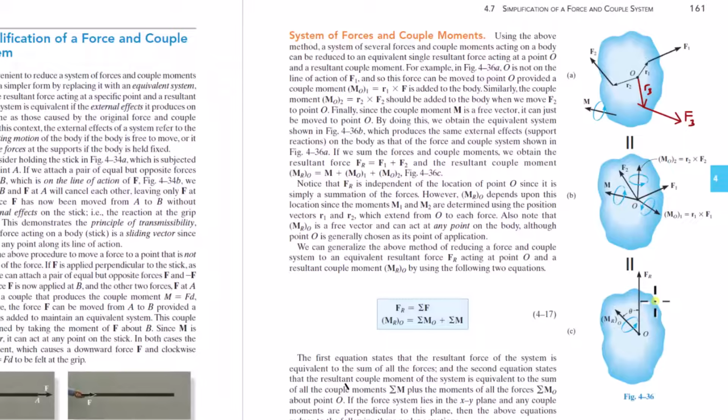Again, you might say, well, what about moments? What about regular moments? Moments come from forces. You see the body. You haven't calculated any moments yet. It's just a bunch of forces all over the place, and then you can have couples. If you want, you can reduce that down, simplify it to one force at a point, and at that same point there's a couple. Now you might be saying, well, wait a minute, why does this couple have to be at point O? It doesn't actually.